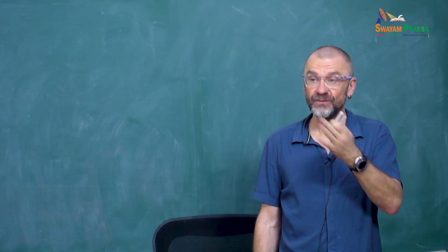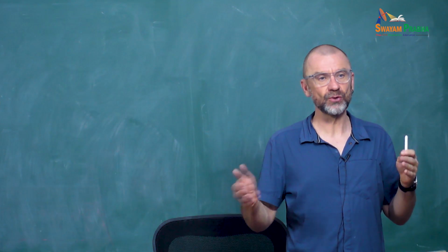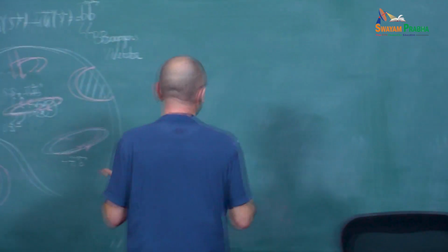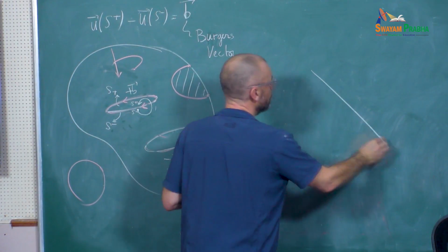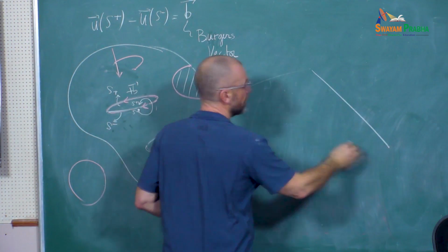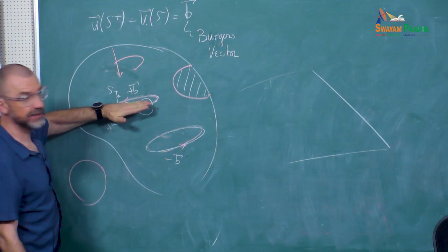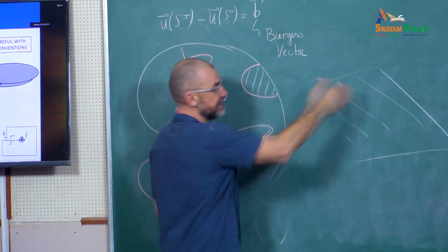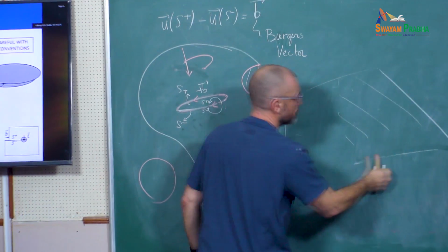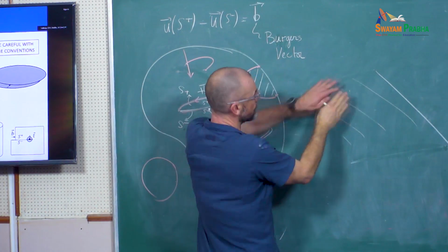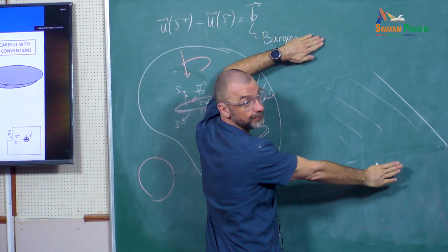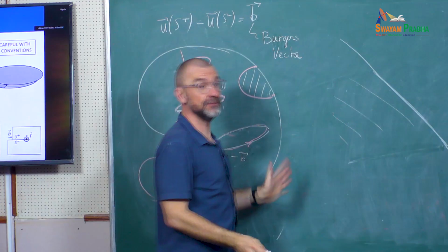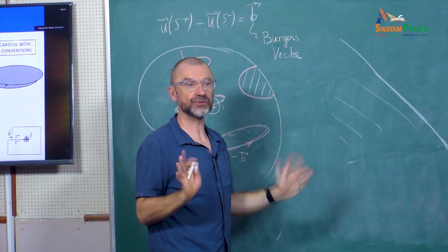Now, very often, and in simulations also, we look at straight infinite dislocation. So what is a straight infinite dislocation? Well, to form a straight infinite dislocation, you need to have a cut surface. I'm going to call this the cut surface. The cut surface has to be semi-infinite. So I've put limits here, there shouldn't be any limit. If I have a cut surface, which is a half plane, then what borders the half plane is a straight infinite dislocation. So that's our straight dislocation.